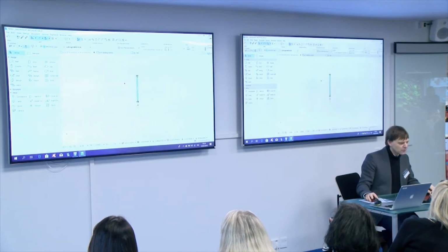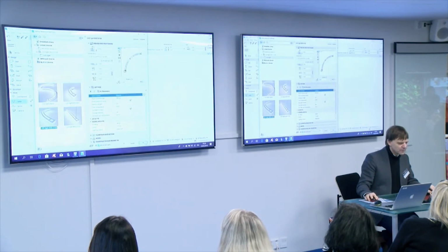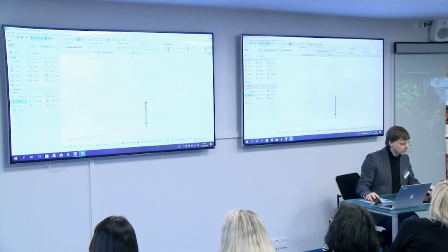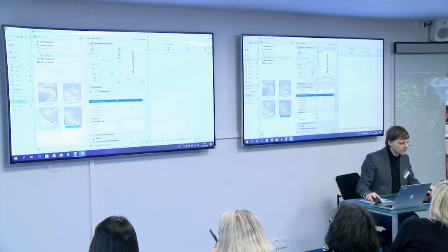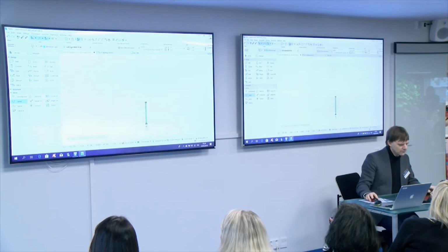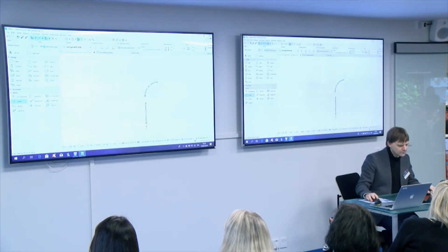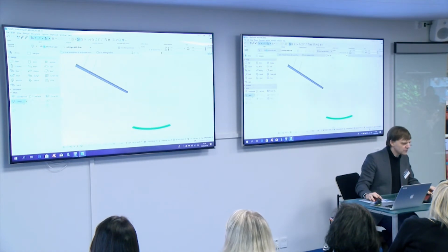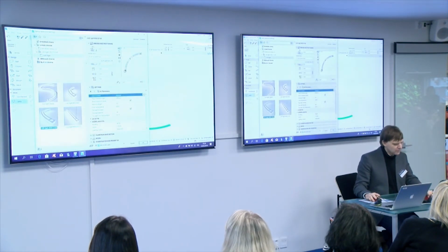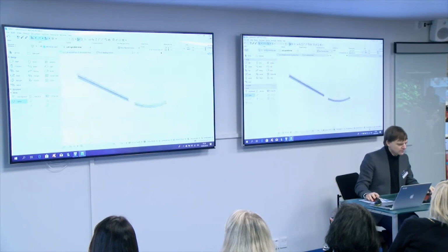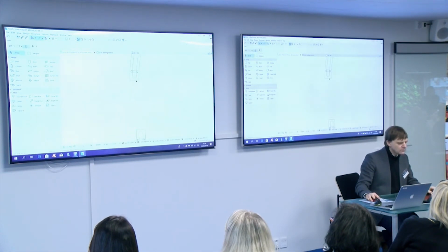But now if we want to go into more complicated shapes, we go into lamp. Let's say, for example, straight. We choose the big arc. And again, I suppose it is probably not the right height. Yes. So we have to change this one also to 2.5 meters from the floor, 500 wire suspension. And now we have to align it manually.